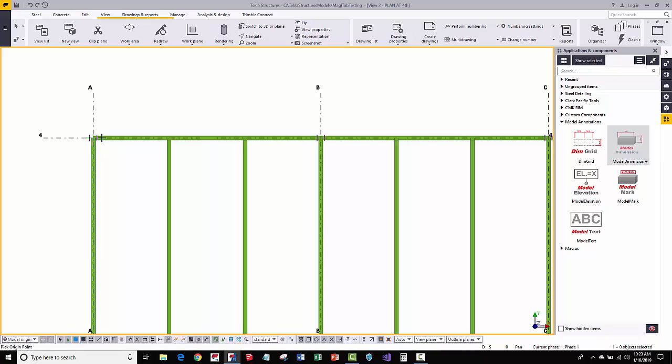So when you first put in a dimension here, what you'll want to do is you'll pick the origin point, and then your Y offset that you put in the dialog box is going to be from that first point picked. And then the second point is basically just any point that defines the X direction. So I'll just pick over here as an example. Then the third point is your y-axis point. Now this is important because if you picked down here, your text will be upside down versus how you probably want it. So the y direction is important. Here I want all my dimensions to go left to right, and I want the text to be above here, so I'm just going to go ahead and click.